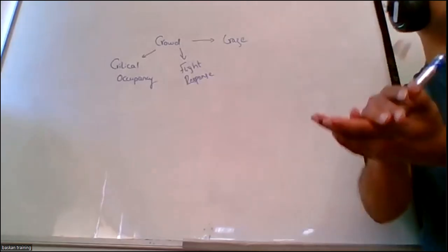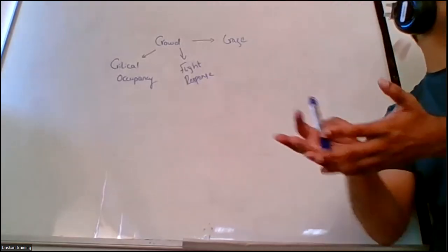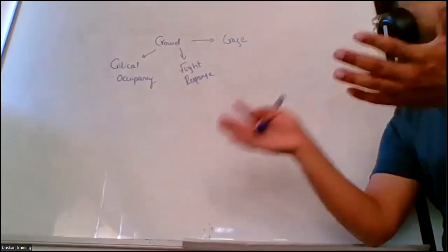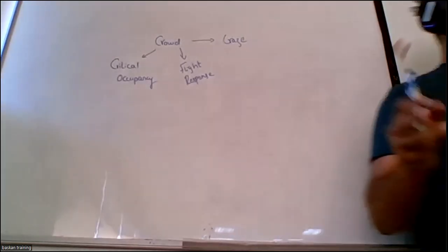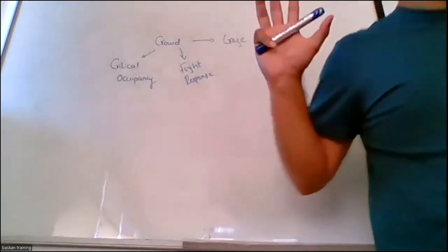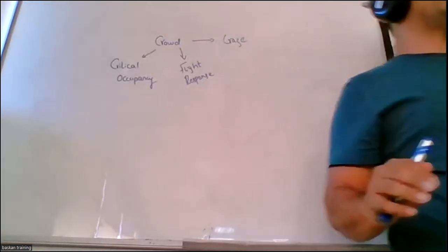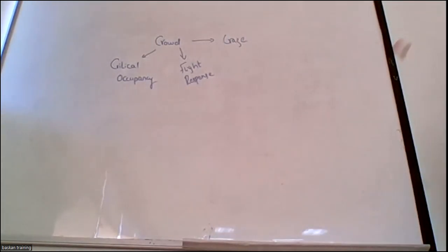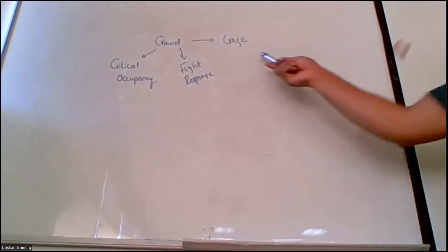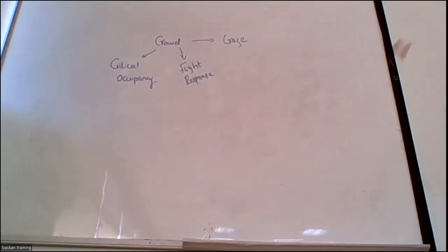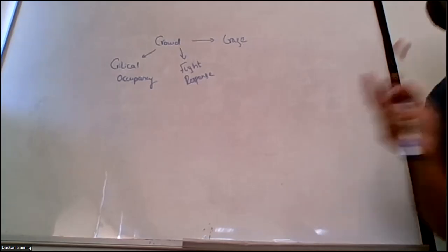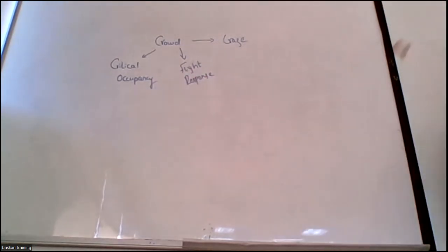People will fall on each other, there will be a stampede situation, and the people coming from the back will start crossing over them. So just to protect the barrier, they have to apply equal force backwards so that the barrier does not break. That is the point of craze. So these are three important factors that can affect the crowd. Whenever any type of crowd situation occurs, your means of egress failure can be based on these three factors whenever you are managing the crowd.